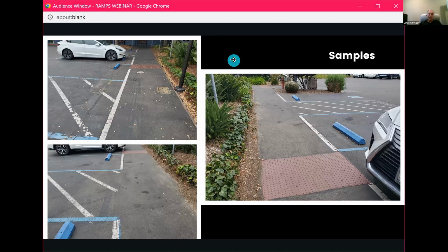The code doesn't allow for the separation to be a curb. It doesn't allow for the separation to be bollards. But if the two surfaces are contiguous, then the solution would be 36 inches of detectable warning. Of course, that means moving this entire walkway.